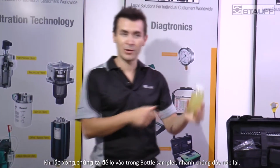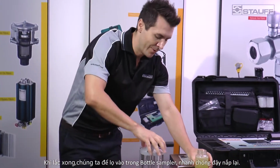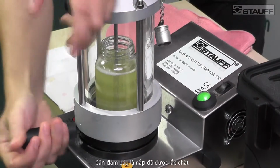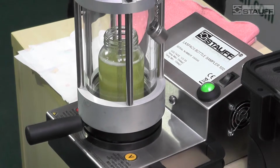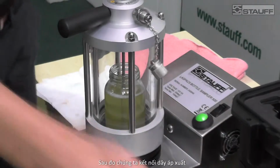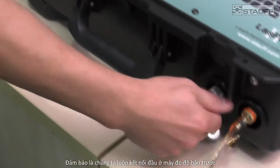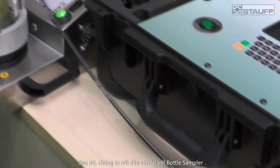And then put the bottle into the bottle sampler, and then very quickly close the lid. Make sure it's closed tight. So then we connect the hose. Ensure you connect the particle counter first, and then connect the other end to your bottle sampler.